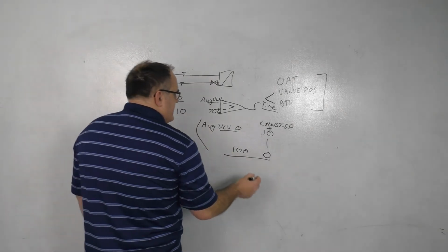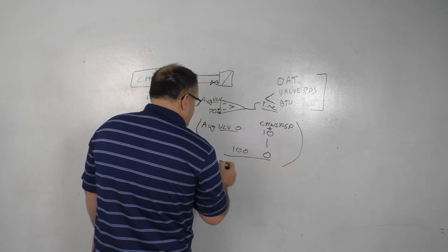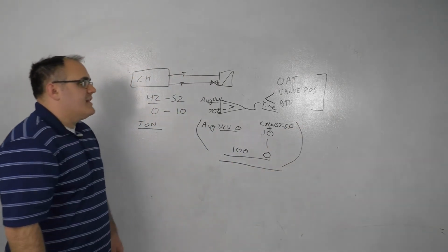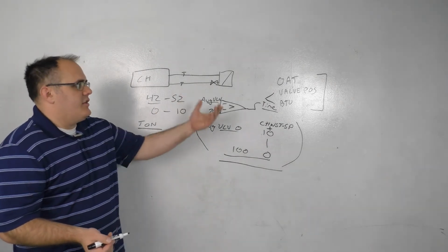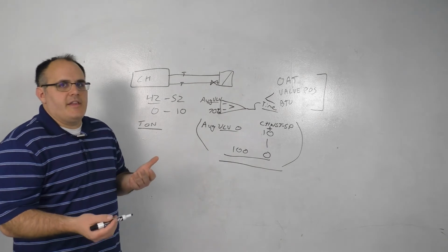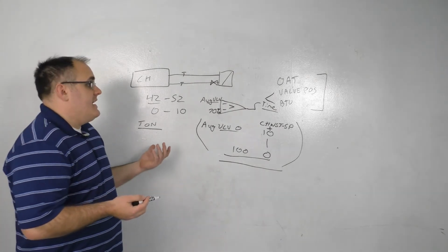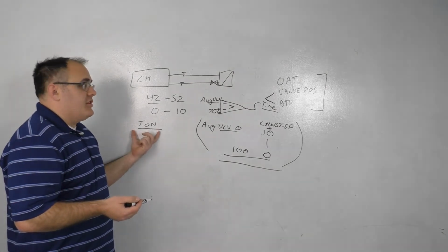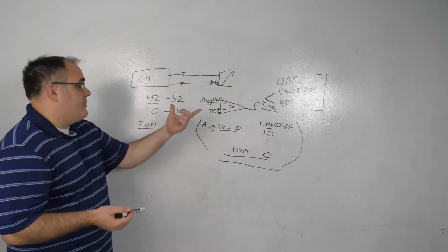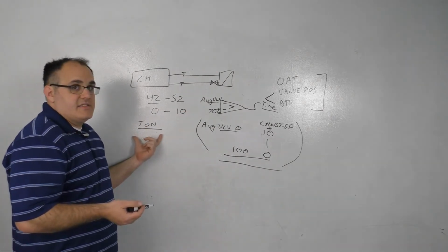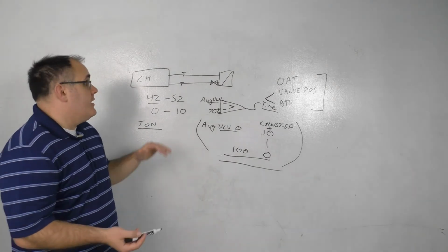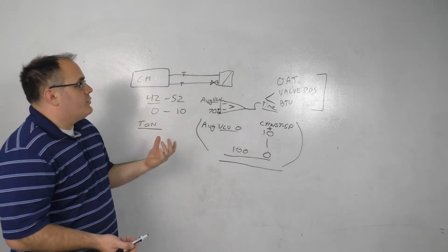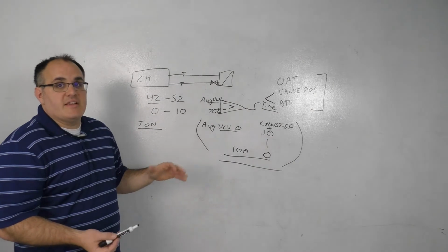I tend to most of the time use the average valve position because it's what most folks know, and they get a little uncomfortable when they have to calculate BTUs and convert it to tons. However, if you're ever going to do chiller staging, that BTU is really nice for staging up, especially if you have a partial load chiller. But it's also really nice for resetting set point as well.